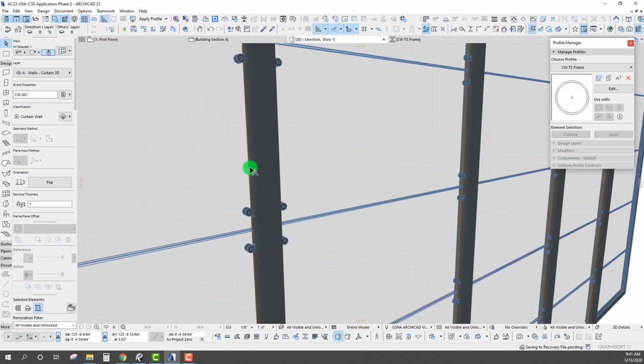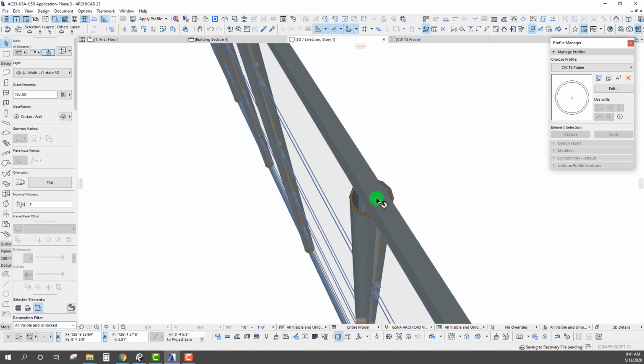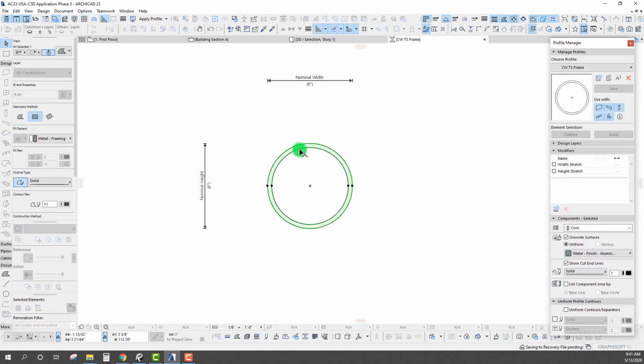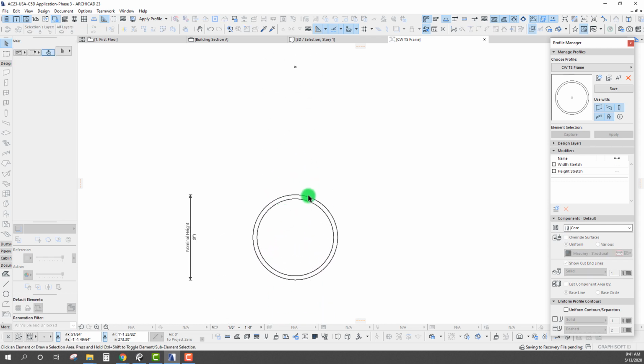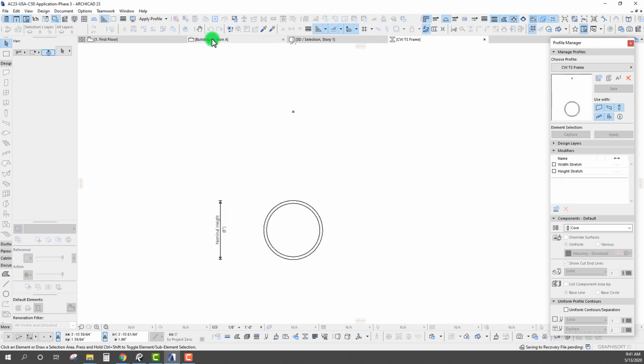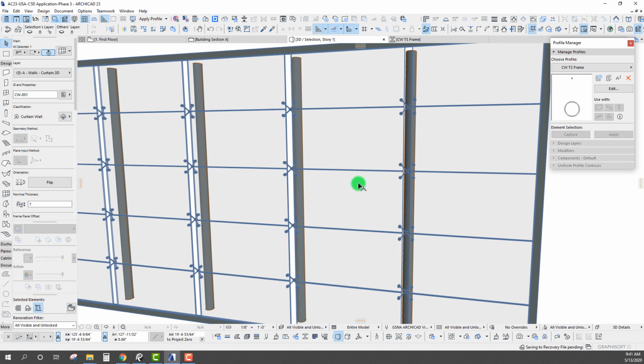We can see that we've now added in that tube steel frame, but it's still right in the center there. So let's go ahead and give this a bit of an offset. So with it selected, we'll just drag it down. Let's offset it. We'll go 1'4" as an offset. We'll set it nice and far back. Okay, and with this, we'll hit save. We'll go back to 3D, and there we go. So we've now offset it.